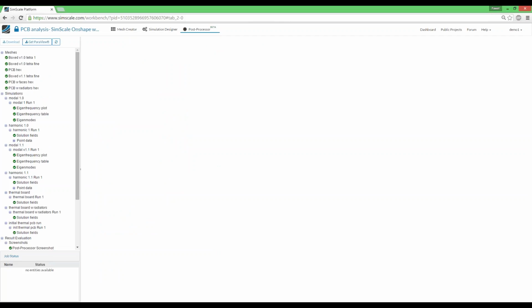Oh, there's a question. I mean the text file, another refinement. So I mean the text file which is transferred to the solver, not the file with the results. So yes, for the structural analysis and heat transfer analysis with Calculix or Code_Aster, you do not have access to those files. They are directly meshed up, packed, and sent so that you get the results. For OpenFOAM, you will get the full structure of the case with the mesh, with all the files that create the simulation.